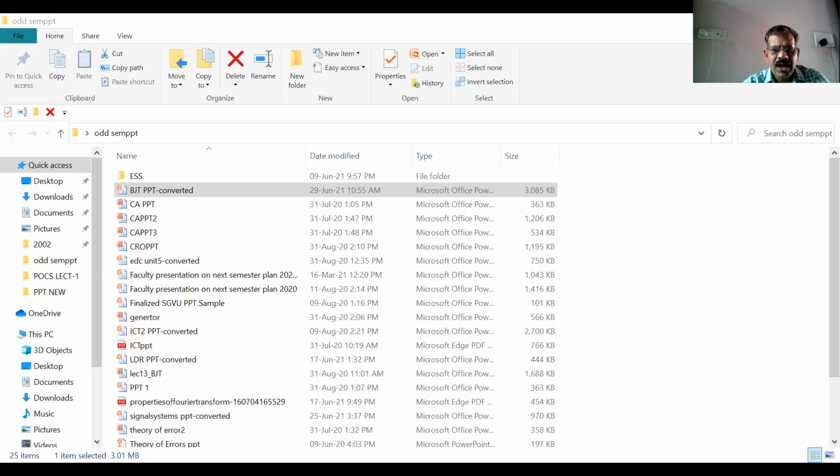This constitutes emitter current IE. And as these electrons flow toward the base, they try to recombine with holes. As the base is lightly doped, only a few electrons recombine with holes within the base.